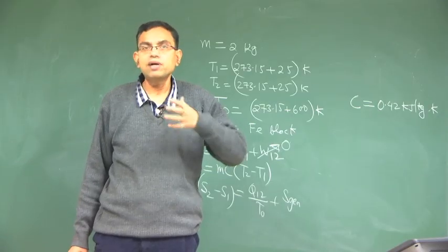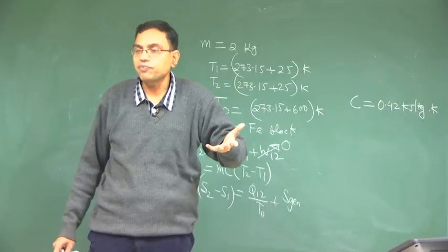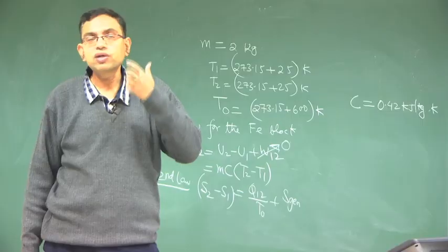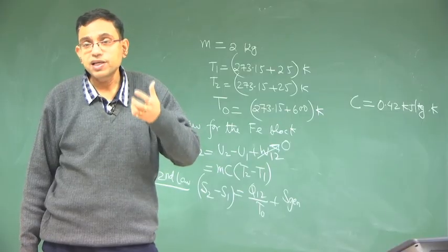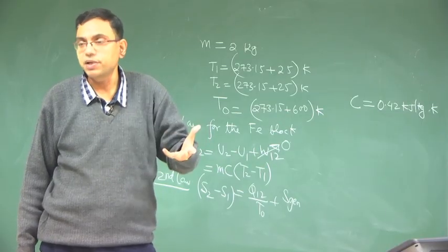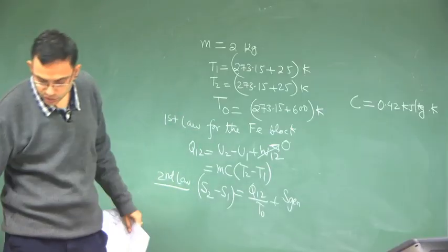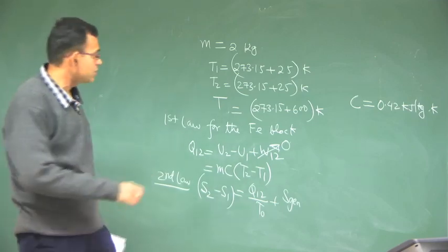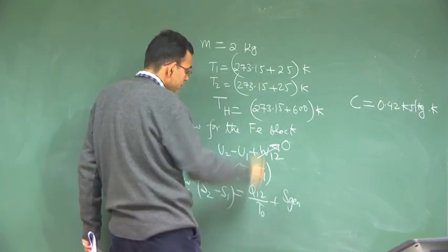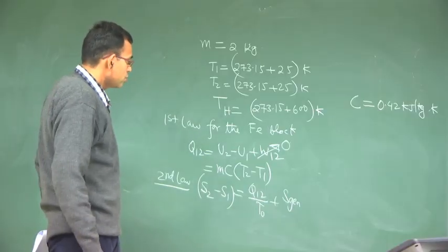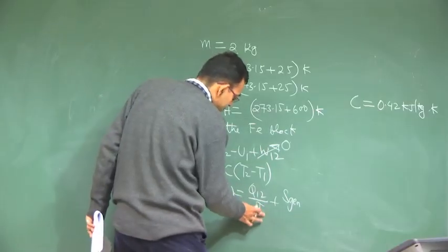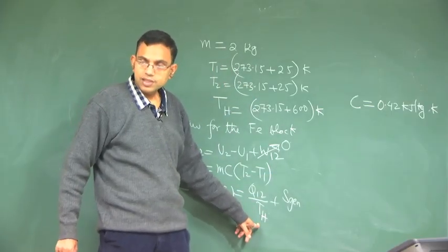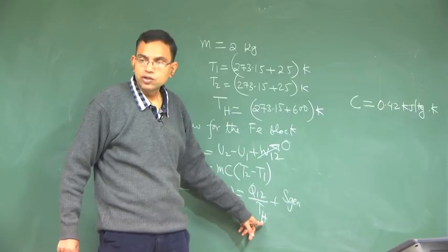You could calculate irreversibility by taking the heat source as the reference temperature, but that is called as immediate surrounding. Normal tradition is to calculate irreversibility with respect to the actual ambient temperature as the reference temperature. So, if we do not choose this to be the ambient temperature, it is not clear in this problem statement that this is not the ambient temperature. So, in that case the heat transfer is taking place with this thermal reservoir and not T0, right.